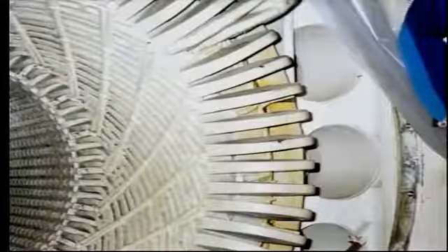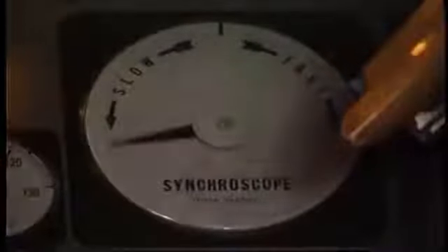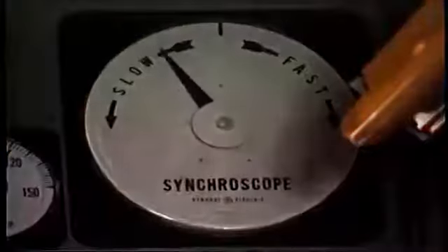The windings may try to twist during heavy power surges or electrical faults on the power system. Similar distortion of the windings may occur if the generator is incorrectly synchronized, that is, connected to the system when it is out of phase with the system. One problem that can occur on generators is the loosening of the windings with resultant vibration and increased temperature rise and perhaps damage to insulation. Checking the conductor wedges for tightness is an important maintenance item during overhauls.